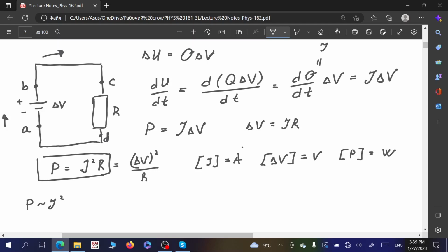But then obviously you don't want to provide such a voltage in apartments. That will not be a good solution, so you need to step it down. There is a sequence of transforming systems which step it down first to 10 kilovolts, then redistribute it at a local grid, and then close to consumers it is stepped down to 220 volts between the phase and 0, or 380 volts between two phases, which are delivered directly to the consumers.